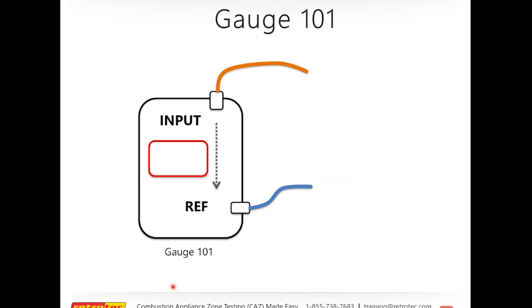If we're just using a pressure gauge, a generic looking gauge where we have an input and a reference, the fact that our reference could be positive on the outside, or that we could have a huge pressure on the outside, could make the pressures on the inside seem negative with reference to the outside, even though it might not be a negative absolute pressure, or vice versa.